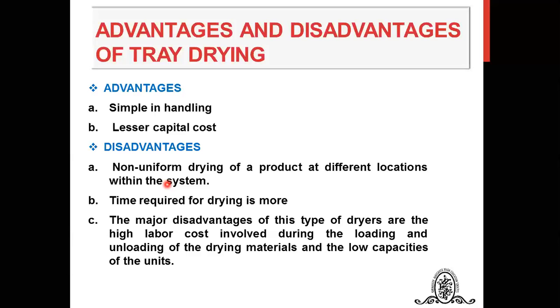The next disadvantage is that the time required for drying is more, and the major disadvantages of this type of dryer are the high labor cost involved during the loading and unloading of the drying material and the low capacities of the units.